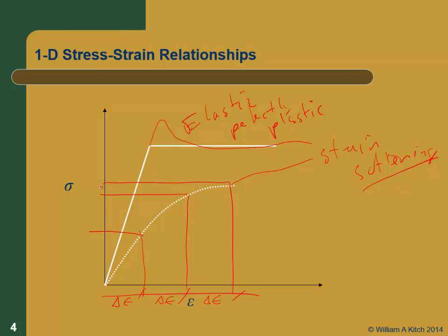What material looks like that? Anybody in CMT? Concrete. This is a stress strain curve for a concrete cylinder, right? It's exactly what it looks like. It fractures right here. So as you get increased stress, it actually gets softer. The modulus goes down.